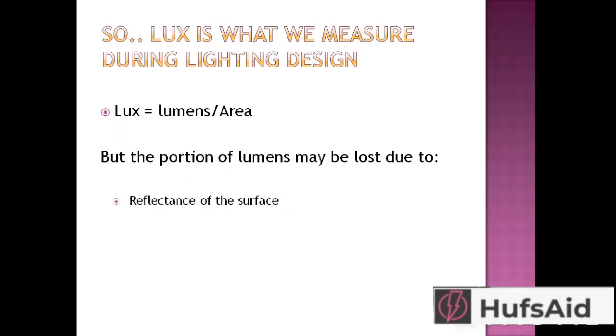It also depends on the texture of my reflecting surfaces. Say I have marble flooring or tiled flooring, then the reflectance of those floors would be more. And say my whole house is painted with oil paint, then oil paint is usually smoother than normal paint like distemper, and the reflectance would be more. So the final word is that the color, the texture, and also the frosting of the fixture all contribute to the loss of lumens.